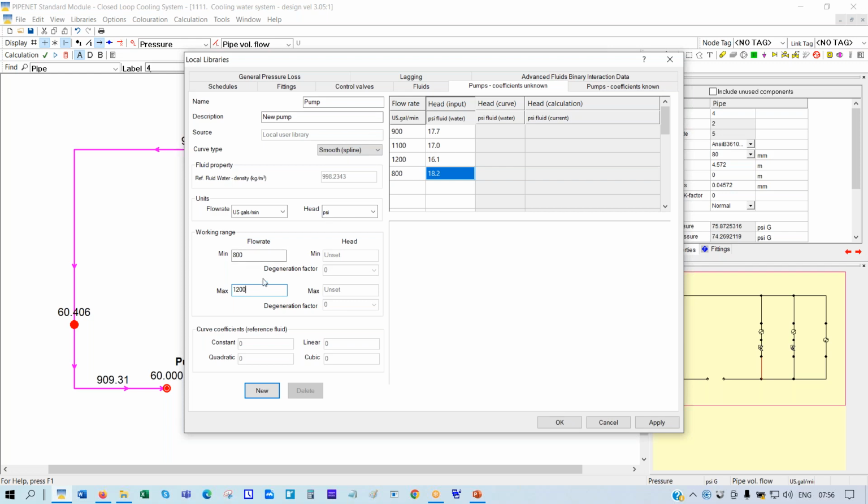It depends on the efficiency, and also something called the run out point, because every pump has a run out point, and if you try and operate the pump with a higher flow rate than the run out point, then the performance of the pump will deteriorate very quickly. It can vibrate and so on. So it is ideal to operate within the preferred range for the pump, and that's what I'm specifying here. And this minimum maximum do not have to be the same as the minimum maximum here.